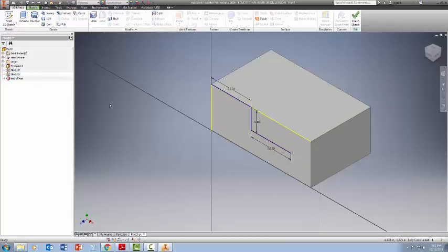Okay, a common problem is that you'll have 2 different sketches and you're trying to do 2 different things. It doesn't know that they're working together. It just thinks that they're completely separate. If that happens, don't panic. What you can do is either go back, erase all of sketch 3 and just work on sketch 2, or you can make some lines in sketch 3 to make it think that it's part of sketch 3, and I'll explain that in just a second.